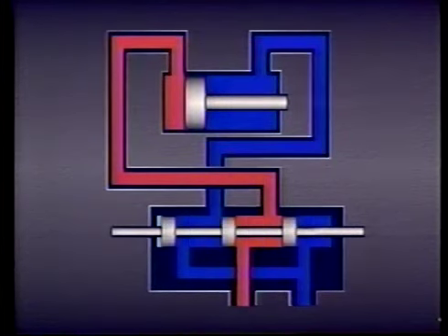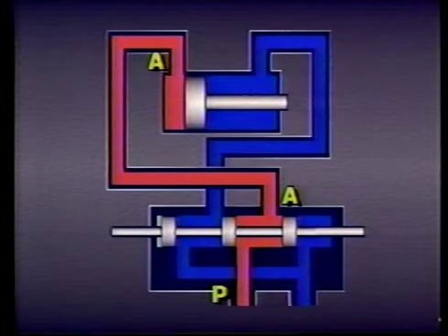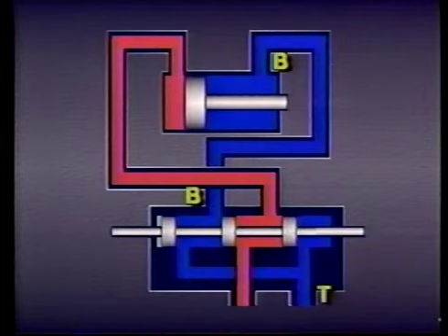When this happens, the passage from the pump to port A on the valve and port A on the cylinder is connected. At the same time, the passage to the tank from port B on the cylinder to port B on the valve is connected.